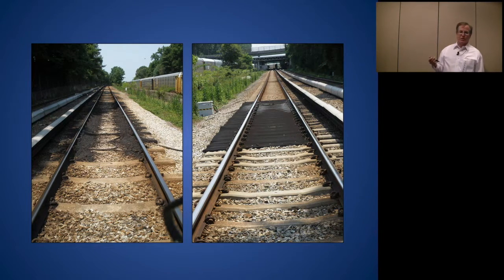You get dust and dirt and bugs and other stuff in there, and rail. There's iron that comes off the wheels from rail wear. And that turns into a pretty good stray current area. Well, I put some geo fabric there. You can actually clean it every once in a while, so it makes it maintainable.